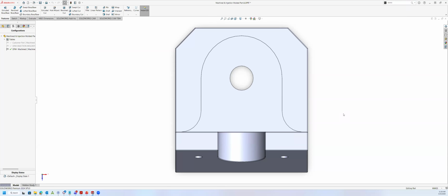Standard tolerancing is typically plus or minus 5 thou on a CNC machine. Not a 16th or a quarter inch, but a little tighter still. As I mentioned, that's just standard. If you want to get tighter than that, that's when it will be paired with increased costs.